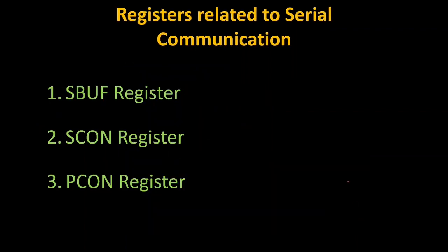So in general, what are the things in terms of registers which is being used? SBUF register, which is going to be your buffer data. If it is going to be transmission, so transmitting data, we have to put it inside your SBUF, and we will be keeping it as a temporary buffer. And after that, we can send the data.